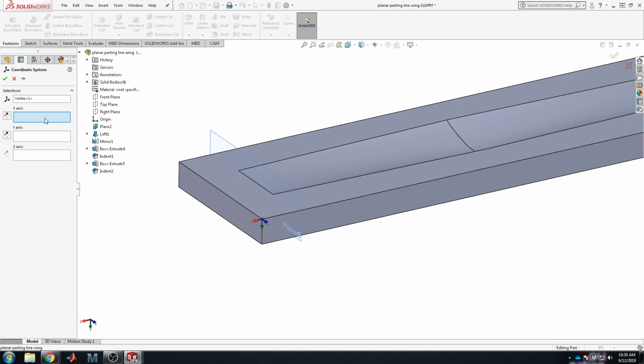So we'll move on. The X and Y axis, this is something to check with your machine, because sometimes the entire direction the gantry moves will be the X axis, sometimes the traverse direction will be the Y, and then sometimes the machines have it switched. So just check your machine setup. Look at a code that you know how it ran on the machine or how someone else has run it before on the machine. In this case, I believe on our machine, the X axis is the long axis, the Y axis is the shorter axis, and Z would be positive up.